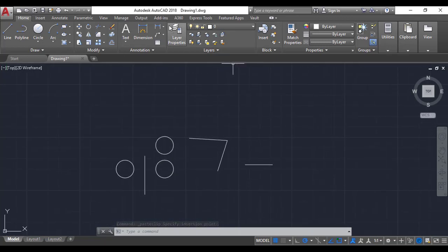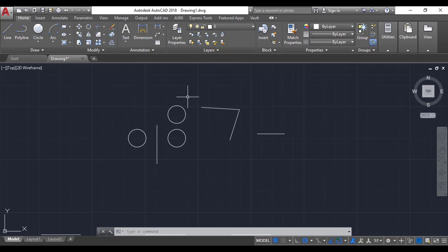We got the layers panel over here. From here on, we can create the layers. The layers we create is just for referencing. So maybe if you take toilets or bathroom utilities, you can make it one color. You can make furniture another color. You can make all the walls one color, and it all categorizes everything into one unit.